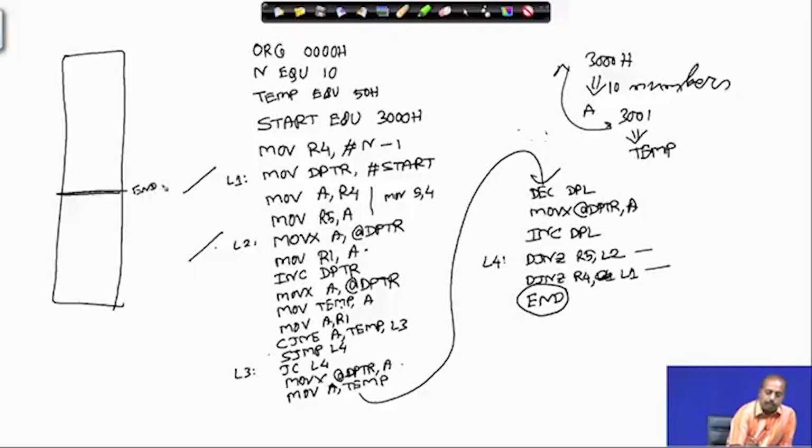then at this point I put an end in my assembly language file, so that this part is not translated into machine code. But I do not delete this part, because later some bug may come up, or some augmentation may have to be done, and then this routine will become part of this routine.